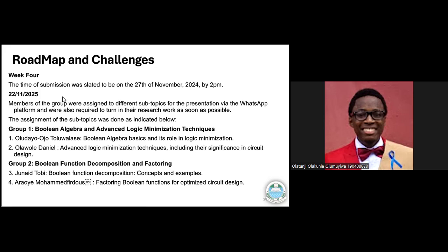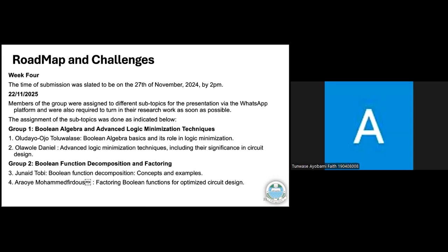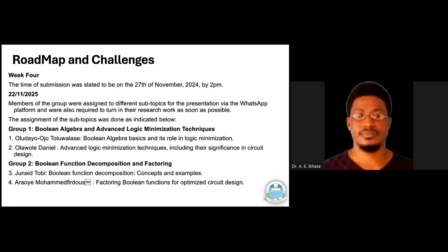It's just the usual: you have your input and then you have your output. When you are done with the algorithm, it will give you your answer in sum of product form, basically. The most important thing is that when we talk about Espresso, you want to declare your input in the programmable logic array format. The computer program takes care of the rest, but that's key when it comes to dealing with that.